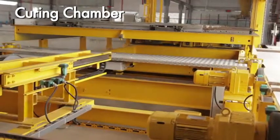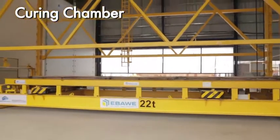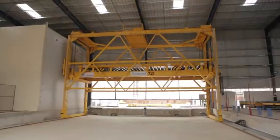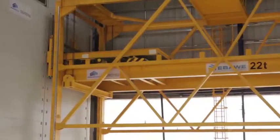Curing chamber. The stacker shifts the pallet from the finishing station to the designated curing compartment specifically meant for the pallet. Curing must be done for an average of 14 to 16 hours. Each pallet transfer is controlled by the master control software.